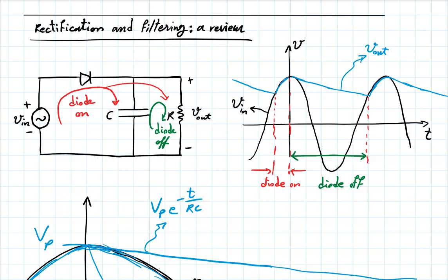But so another question. What if my diode is not ideal? Well, first of all, qualitatively, how does the behavior of the circuit change if I have a real diode, not an ideal diode? So something that has that exponential voltage-current relationship, or dependence of current on voltage.